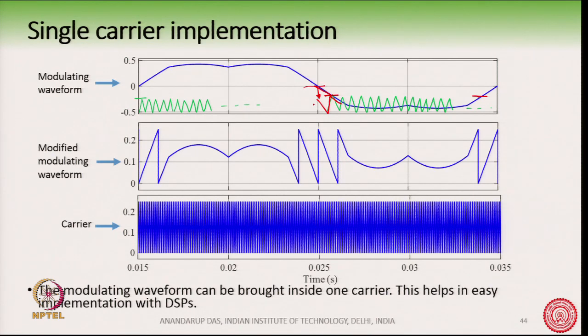So, when it crosses the second carrier, this is the boundary of the second carrier, and then we go to the third carrier. Then I have to do 2 shifts or 2 pushes down. So, from there, this part of the waveform here, I will push it down inside the green one, and that is what this is doing here, 2 shifts. This part of the waveform is obtained by 2 shifts down, and the last part is where the fourth carrier resides. Here is where the fourth carrier resides.